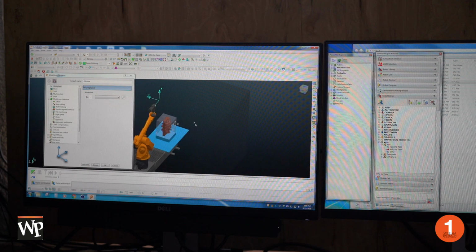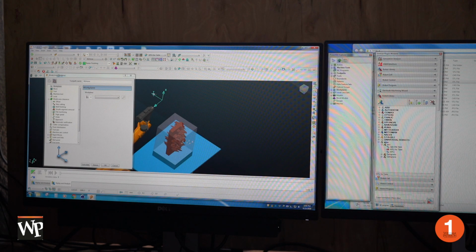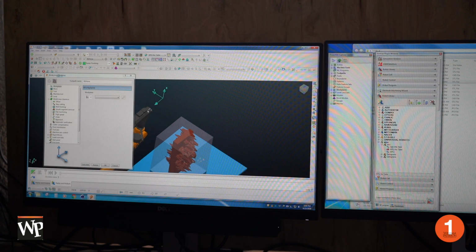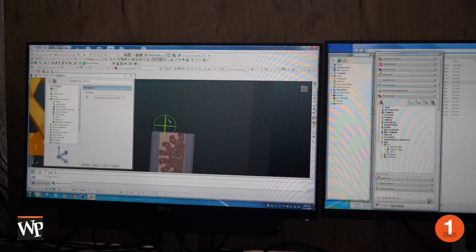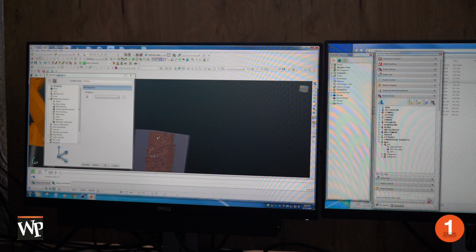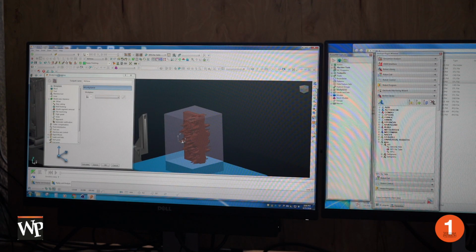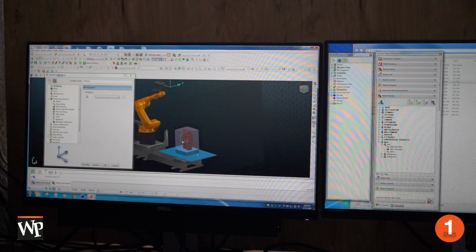So that's for the world. And then we have one for our tool, which we can see here. And Z faces into our spindle. So when we create a work plane that we're going to use, we want our Z to face away from our model, to face the same way that the one for our tool does.